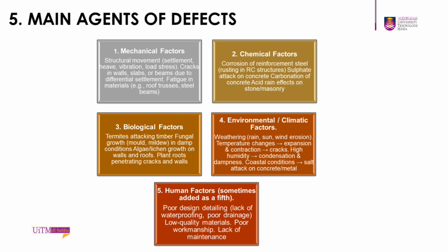5. Main agents of defects. 1. Mechanical factors: structural movement, settlement, heave, vibration, load stress. Cracks in walls, slabs or beams due to differential settlement. Fatigue in materials, e.g., roof trusses, steel beams. 2. Chemical factors: corrosion of reinforcement steel, rusting in RC structures, sulfate attack on concrete, carbonation of concrete, acid rain